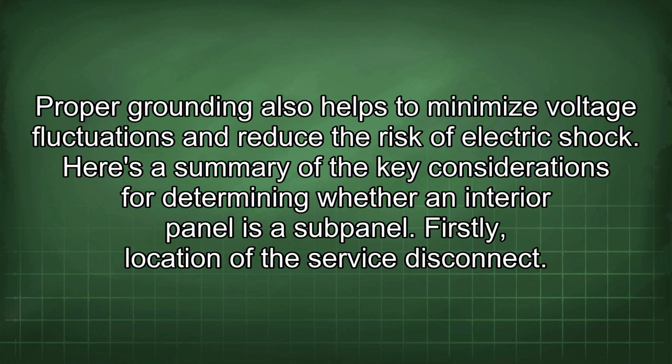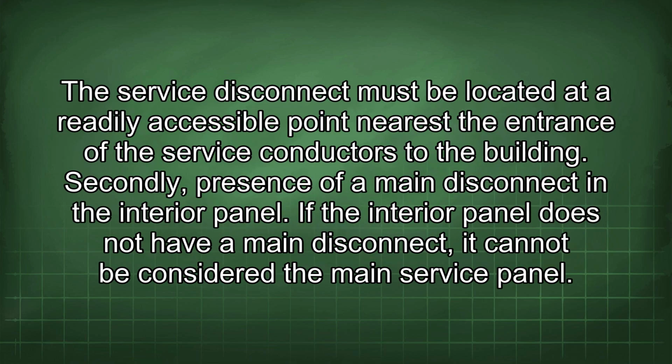Here's a summary of the key considerations for determining whether an interior panel is a subpanel. Firstly, location of the service disconnect. The service disconnect must be located at a readily accessible point nearest the entrance of the service conductors to the building. Secondly, presence of a main disconnect in the interior panel. If the interior panel does not have a main disconnect, it cannot be considered the main service panel.